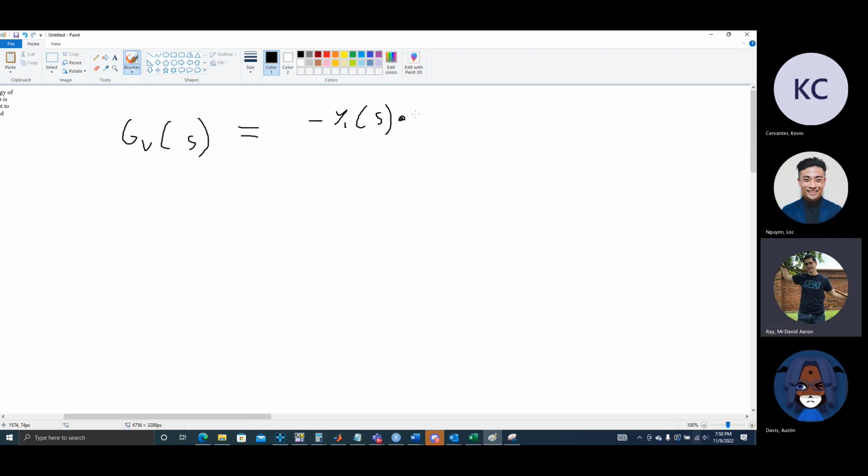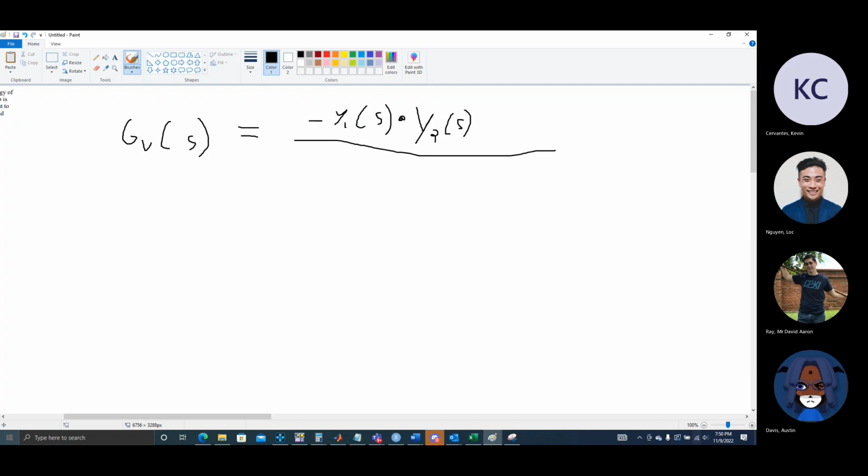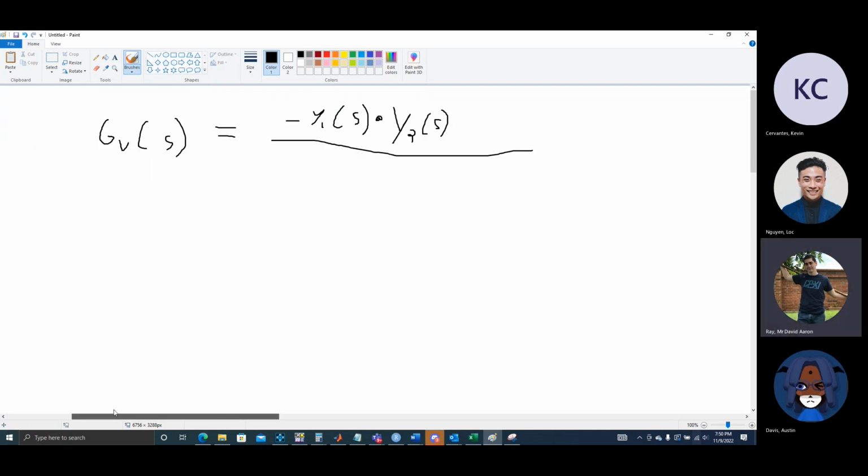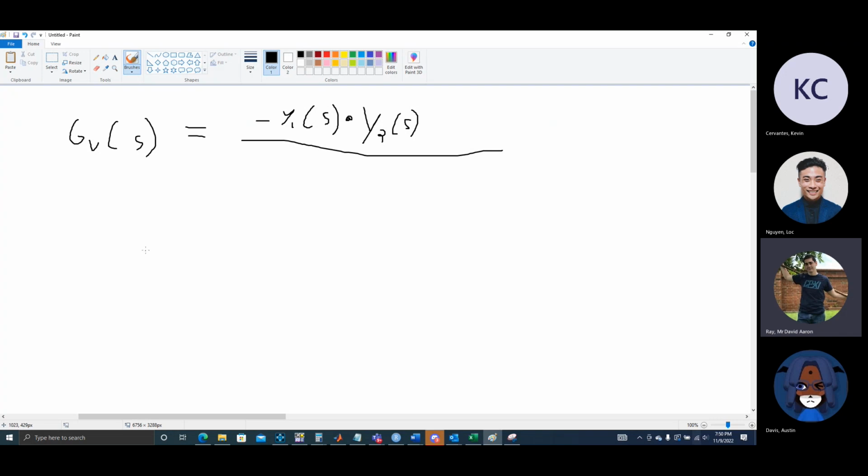Awesome, awesome. So pretty much what you're doing here is taking each resistor and capacitor and turning it into either an admittance or an impedance, depending on the equation. For this topology, the gain equation given is going to be in admittances.